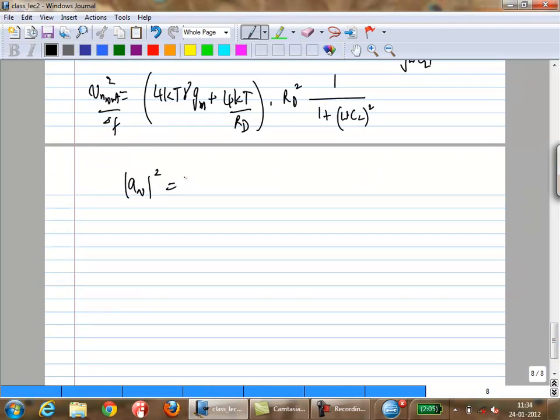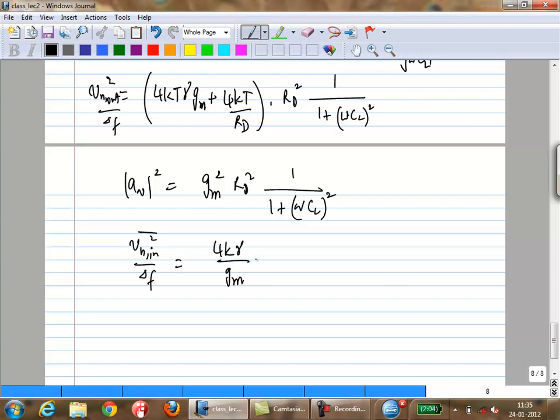What is the gain now? Again, it turns out gain is also, right? Now the gain is also frequency dependent. The output noise is frequency dependent. But because they have the same frequency dependence, the input referred noise is now going to be frequency independent. Okay? Why is this happening? Because you're producing your noise first, and then the output pole happens to come after the noise sources. So both the signal and the noise get multiplied by the same transfer function of the output impedance. So the input referred noise happens to be frequency independent. Okay.